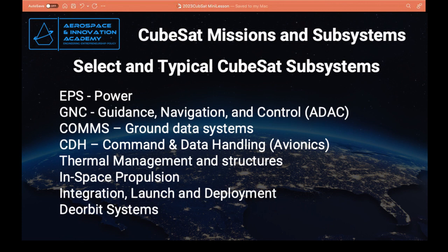What exactly is avionics, just to be clear? Think about it as the processor or the computer, the brains of the CubeSat. Think of it as the brain and the nervous system of the satellite. It manages the data. And because we're in space and there's more radiation, we often need components that are hardened to radiation or are tolerant to upsets and can reset themselves. So I'm imagining like a motherboard kind of thing on a computer.